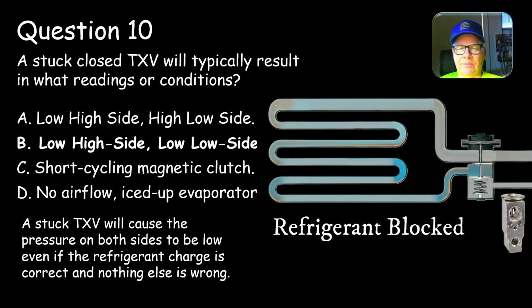And that's how you do it the right way. You don't want to vent the refrigerant to the atmosphere or anything like that, even though it is venting when it leaks. But they couldn't find her leak, because it's hard to find a very small AC leak. You use dye and be really careful. If it's leaking in the evaporator area, you're not going to see it unless it drips on the ground from the evaporator drain.